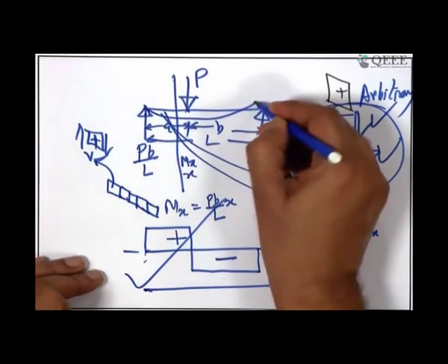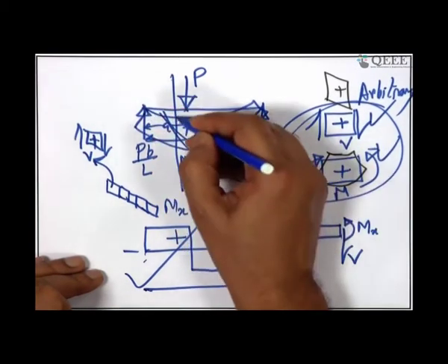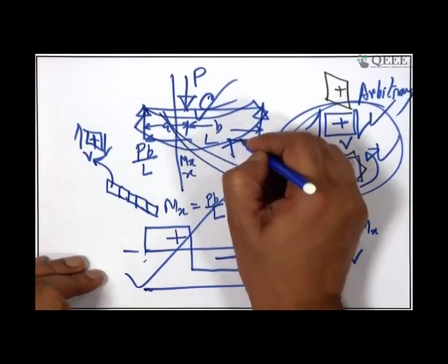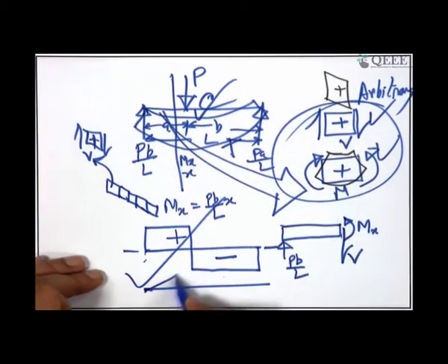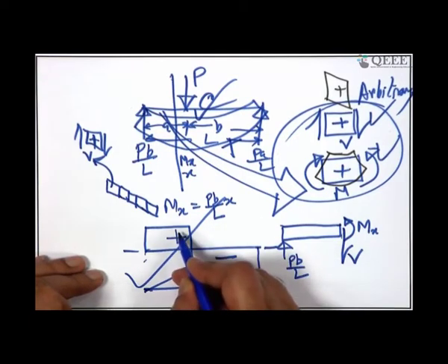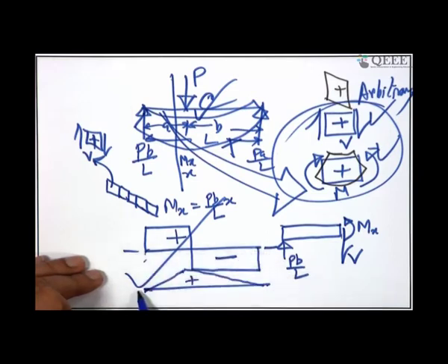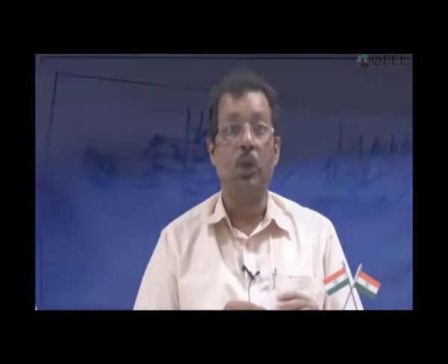So, the beam will bend like this. That is why this is in compression and this is in tension. If that is so, I draw the bending moment on the compression side; it is just arbitrary, and many of the books do that. So, drawing the positive shear on the upward side of the reference line and drawing the positive bending moment onto the compression side is absolutely arbitrary and should be acceptable to us. Now, to answer the query from John: yes, the sign conventions are absolutely arbitrary, chosen by us, and we are free to choose the other one.